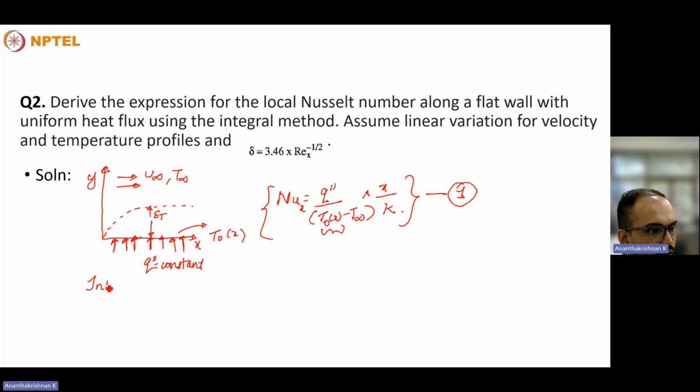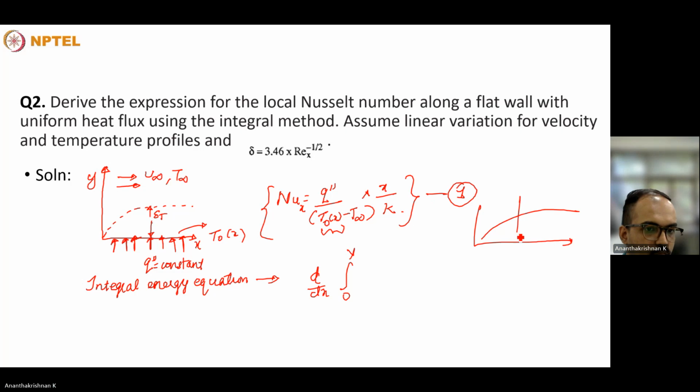The integral energy equation, as mentioned by the professor during his lectures, is given by d/dx of the integral from 0 to y, where we can assume this y to be some distance far away from the wall, of u into (T infinity minus T) dy equal to alpha dou T by dou y at y equal to 0.